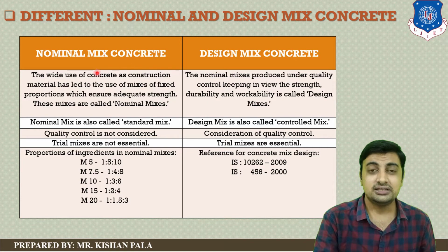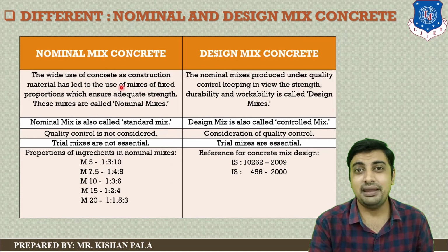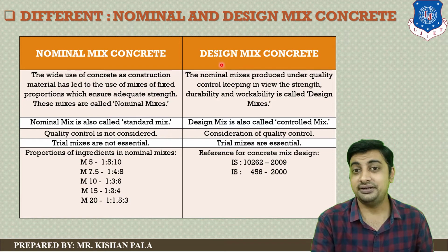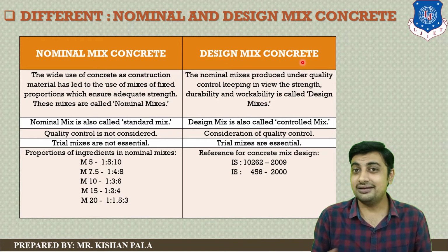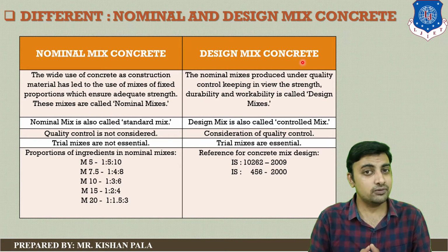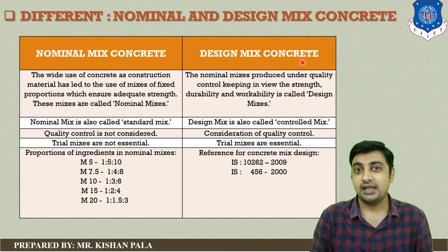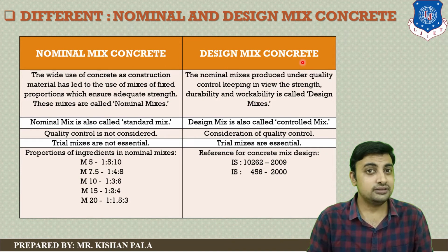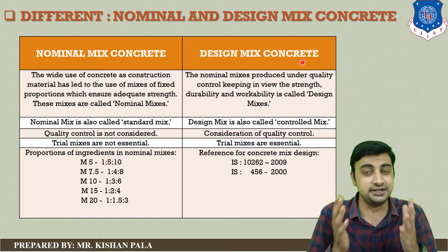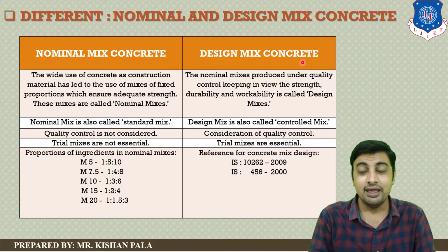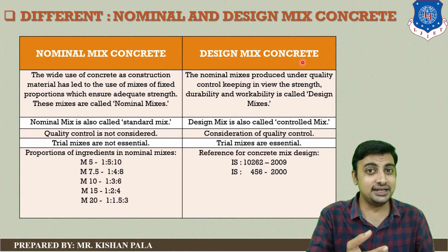So this is the simple method, and this is all about the nominal mix concrete. If we talk about the design mix concrete, if you are doing a larger project, or if you are concreting an important element of the concrete mass, and if you are doing a high-rise building or any important structure, in that case the design mix concrete is required, because in this method you are calculating all the ingredients with